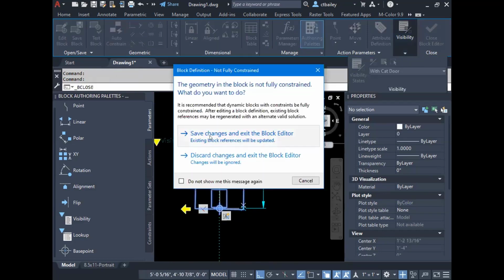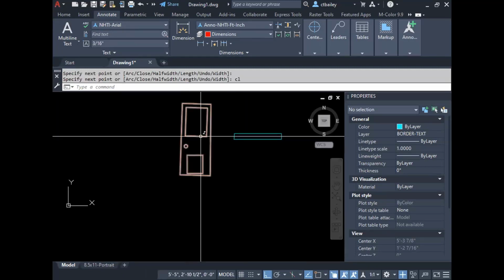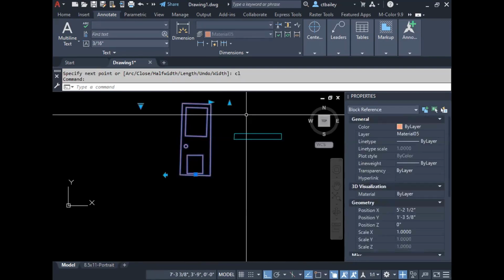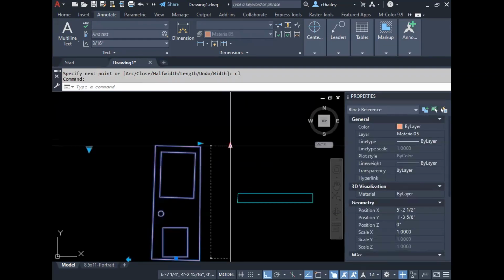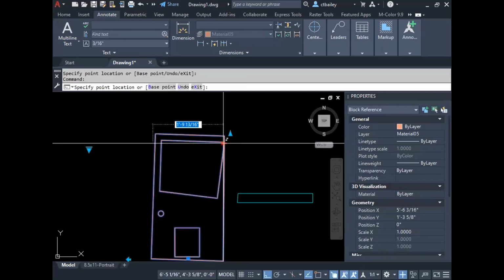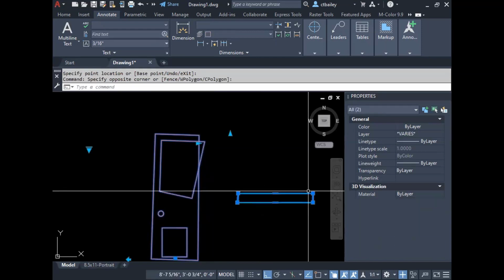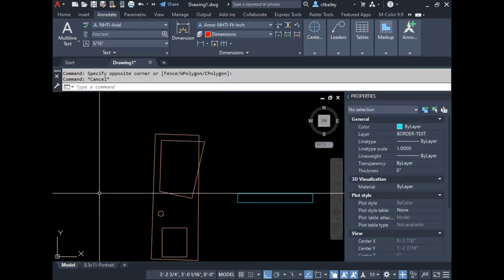What I'm going to do is open up your drawing and see something that looks like your door and something that looks like that. And I'm going to grab it and see how many of the little grip edits you've left me. I'm going to set it up to a 36-inch wide door, 24-inch wide door, whatever. And this block here, the same thing. I'm going to set it up. I want to see the different sizes.